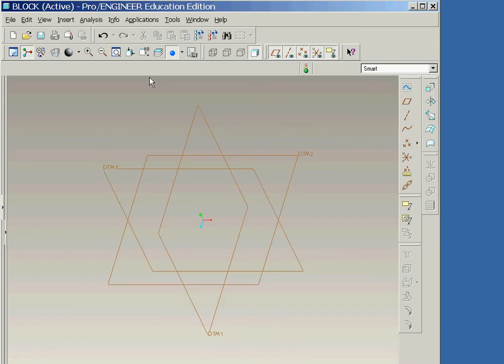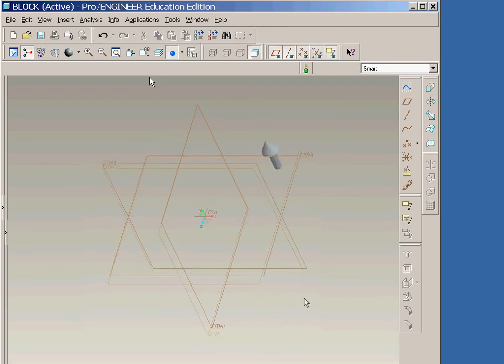Let's take another brief look at how the concept of orientation with datum planes can be envisioned. ProE will often reposition a view based on the direction in which the positive side of a datum plane is pointing. A normal vector emanating from the positive side of one of the datum planes as shown here illustrates the direction that the datum plane is pointing.